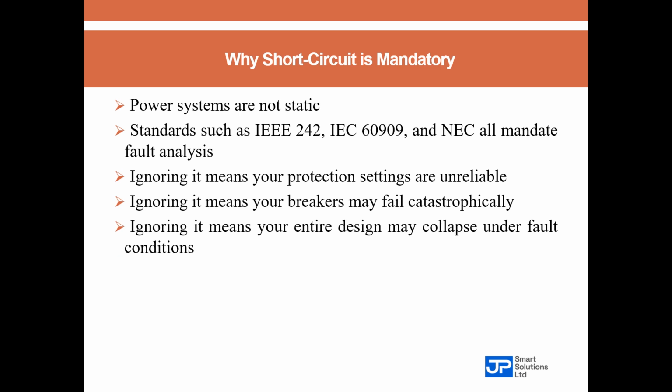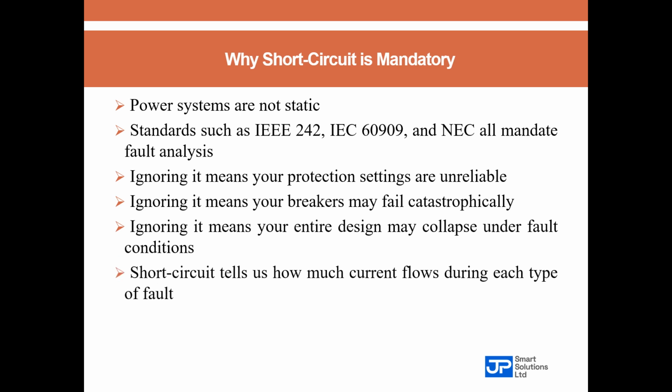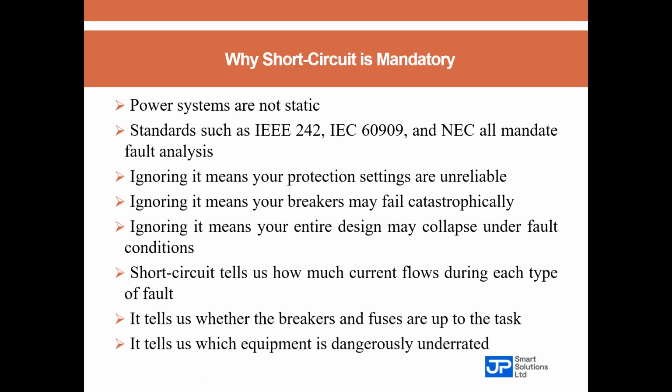Short circuit analysis actually tells us how much current flows during each type of fault, be it a symmetrical fault or an asymmetrical fault. It tells us whether or not the breakers and fuses are up to the task. It also tells us which equipment is dangerously underrated. So if you are not carrying out a short circuit analysis, then you are hoping, not designing a power system.